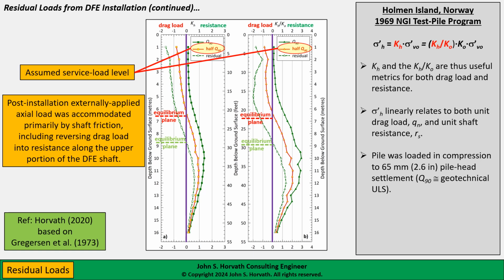And we see here very nicely, with the drag load converting to resistance, that very unique nature of soil, that you could basically take a soil that has, quote unquote, failed, reverse direction of movement along the failure plane, unfail it, bring it to a neutral position, and then fail it in the other direction. And that's what's happening here. The soil went to a neutral, unfailed position, and then was brought to movement in the other direction.